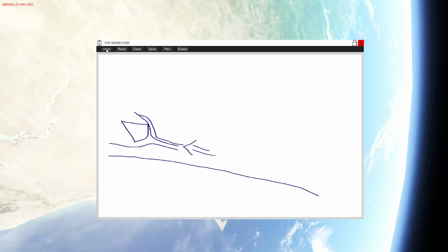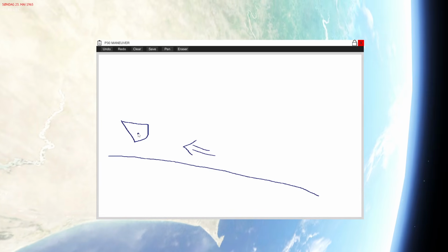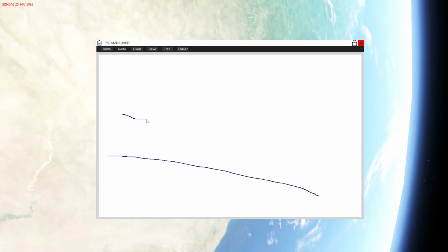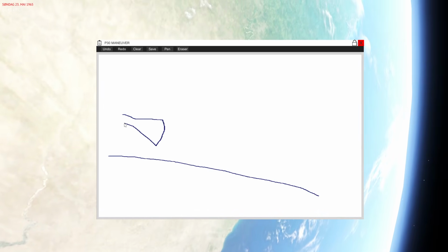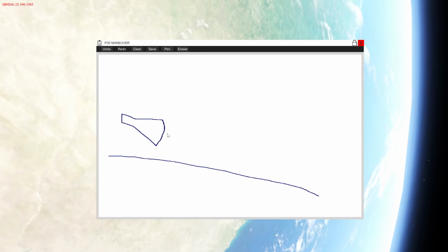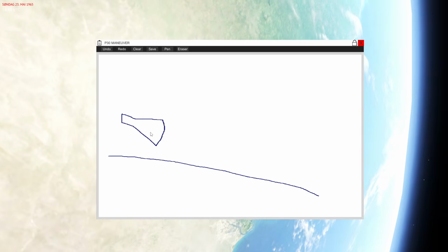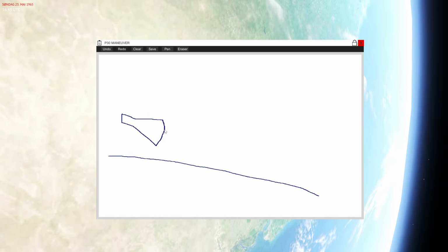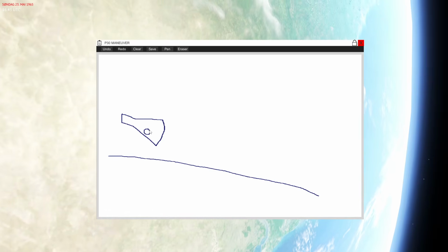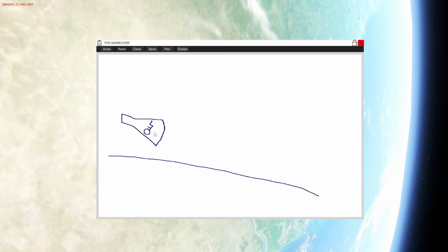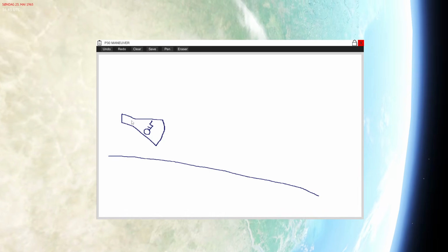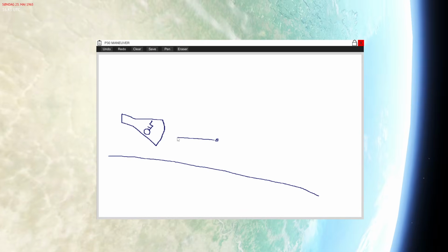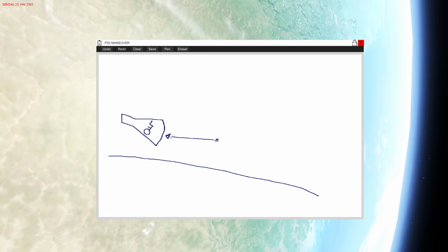The air that travels around us creates this drag. But since we have an offset of the center of gravity, and let me just redraw this capsule slightly better, give us a little bit more room. Since we have this offset in the center of gravity, we can use roll to tilt the spacecraft. If the astronauts are sitting inside of the spacecraft and steering it, the drag will come in here and meet the craft.